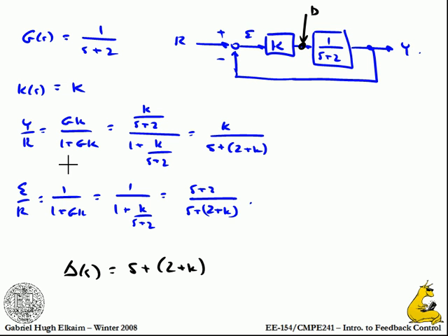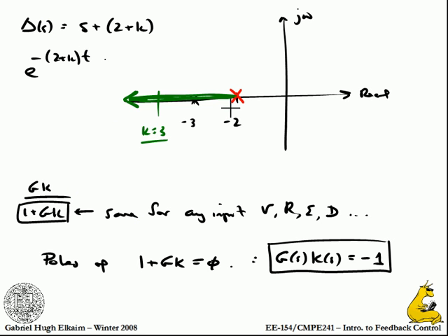Shane, in this example, when you say move the roots around, that means change K? Yeah. In this particular case, all I've got to tune it is K. And with K, I'm fairly limited in what I can do. All I can do is move it along that line. And if I'm willing to make K negative, I go to positive feedback, a destabilizing one, and I can move it in this direction. We'll get to that a little later. I don't want to confuse you, but you can usually do both sides of it. Nonetheless, here I'm fairly constrained.